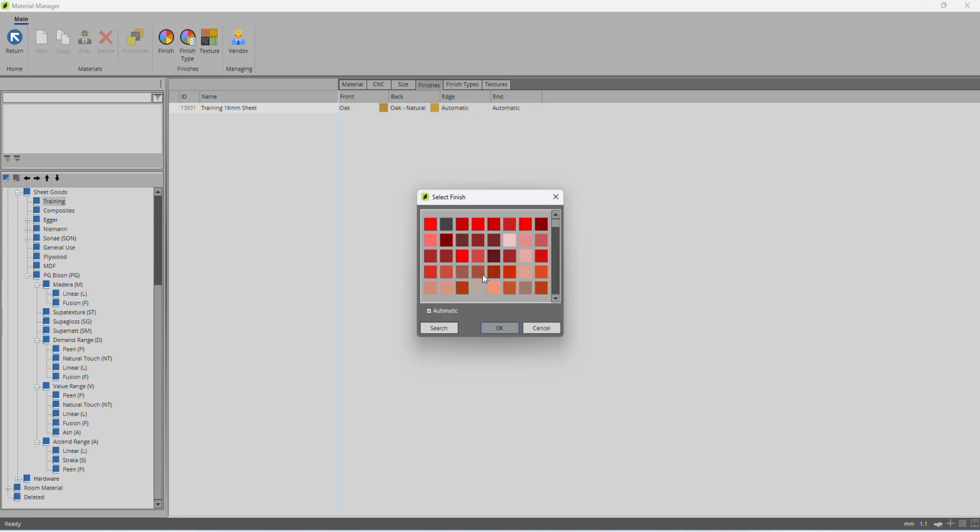What a lot of people actually do is they go and assign a ridiculous color, pink or green or yellow or something. So even in your finished view, it'll automatically show you where there's an exposed edge. That's a good one for designers because they do get busy and don't always check everything. If your construction method is set up correctly, your edging will always be correct. But the problem is you can modify your edging manually in the job as well. So they might have done something that removed the edging, and then that'll show bright green and you'll know, okay, I'm missing edging there.